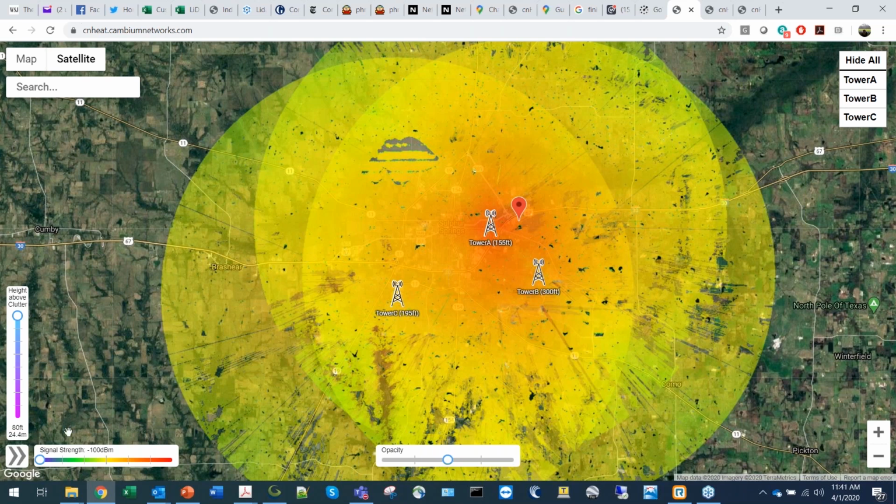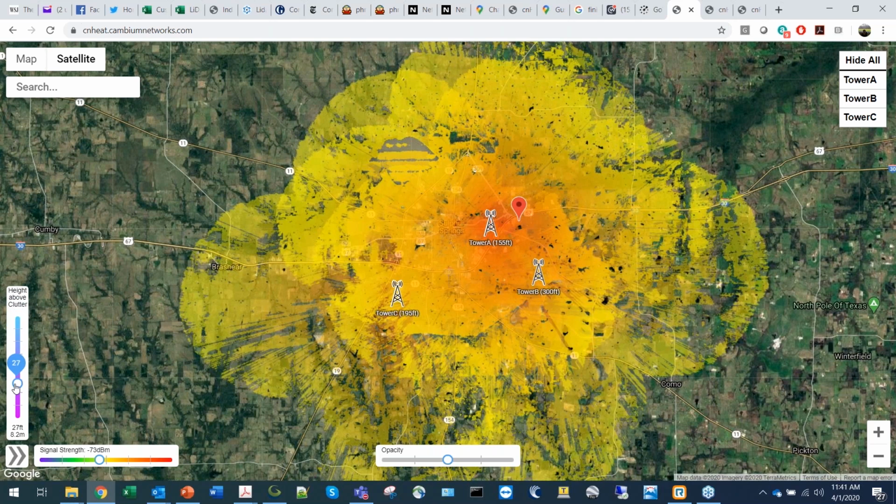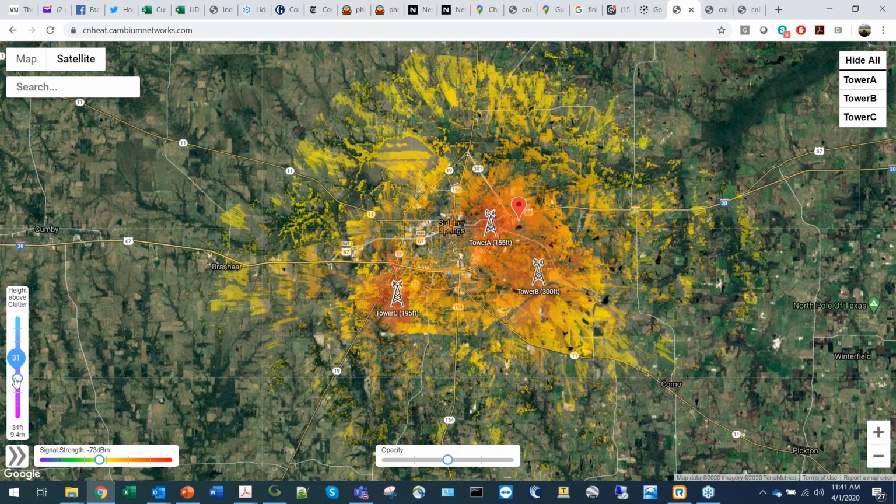Real briefly, if we take a little overview, we have a couple of slider bars, and you can go from showing the RSSI value that you are interested in. Say it's -73, you set it to there. It'll show you the coverage for your sites at -73. And say you're interested in just doing install heights at 30 feet or below. It'll show you the coverage there.